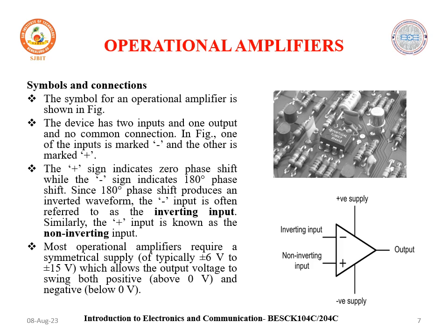Next, move on to the operational amplifiers. As we all know, the integrated circuit operational amplifier, called OPAMP, is the fundamental building block for many electronic circuits. An operational amplifier is a multi-stage, direct coupled, high gain, negative feedback amplifier used to amplify AC and DC input signals. The main applications of OPAMPs: we can use them as active filters, oscillators, peak detectors, comparators, voltage regulators, precision rectifiers, instrumentation and control systems, pulse generators, and square wave generators. So we have enormous applications of the operational amplifier.